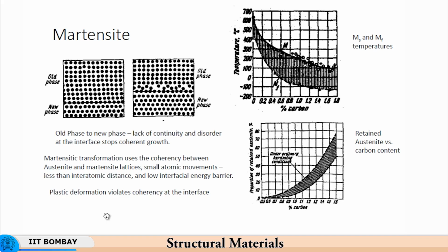The typical domain of tool steel application is here, where the carbon percentages are very high, 1.2, 1.5, one can go up to 1.5 as well, and then you have about minus 120 to minus 125 degrees centigrade or so as martensite finish temperature. So, you have some retained austenite which also does a world of good where impact is involved.